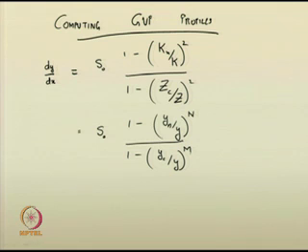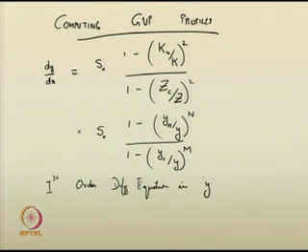So, you can see that this is a first order differential equation in y. We have also seen that it requires one boundary condition to solve, and to solve that, we have described the control sections in open channel flows. One can begin with the control sections where the properties are known initially, and from there one can start computing the profile, like we discussed in the last class.